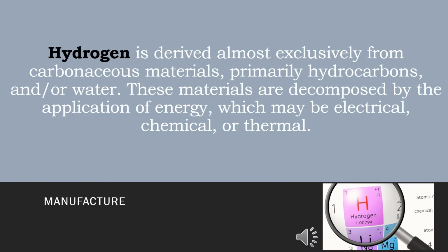Hydrogen or H2 is derived almost exclusively from carbonaceous material, primarily hydrocarbons and/or water. These materials are decomposed by the application of energy, which may be electrical, chemical, or thermal. Examples include electrolysis of water, steam reforming of hydrocarbons, and thermal dissociation of natural gas.